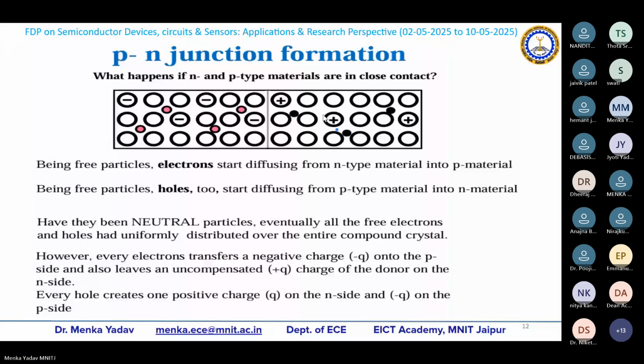Look at this. These are going to move this way. Why are these going to move in this way? Here holes are going to exist. This is N type. So in n type, we have minority holes, and that can be represented like this. pn can be represented as ni squared, small ni squared, that is the intrinsic carrier concentration, divided by Nd. So the more the doping, the less the number of holes.